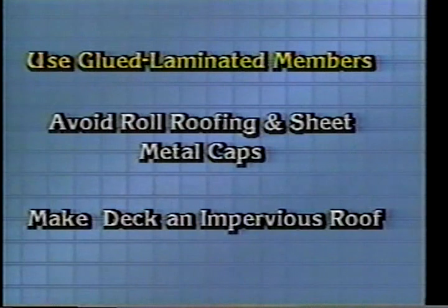When it's practical, use glued laminated members. Avoid using roll roofing or sheet metal caps on stringers, pile, or post tops. And as much as possible, make bridge decks an impervious roof over the stringers.